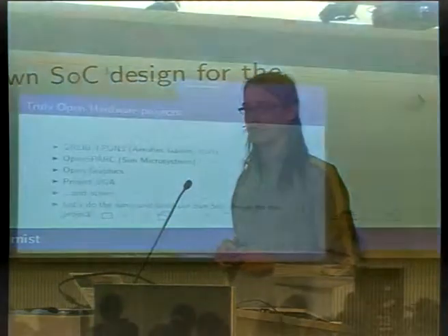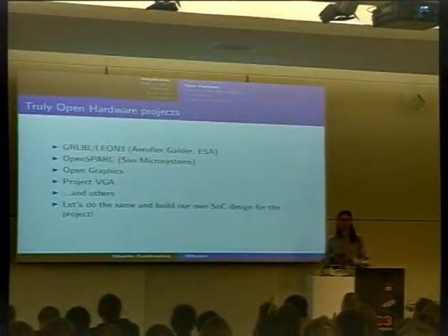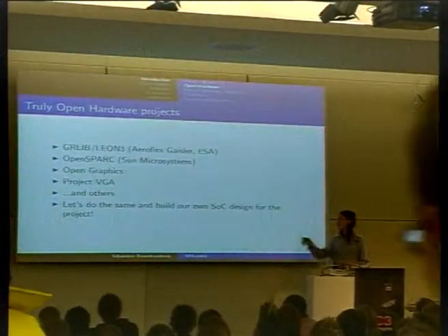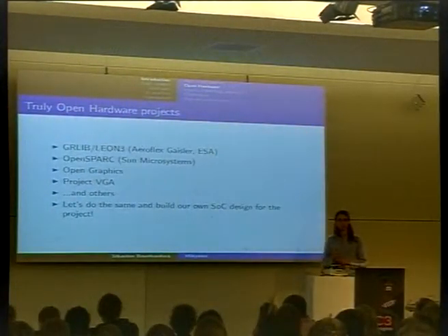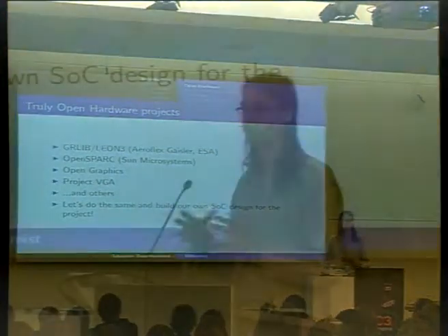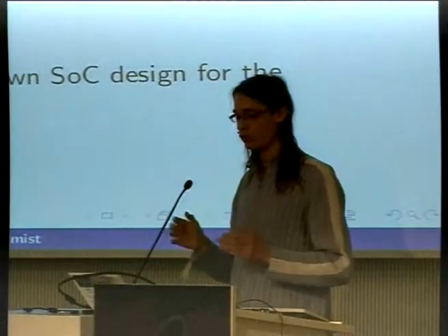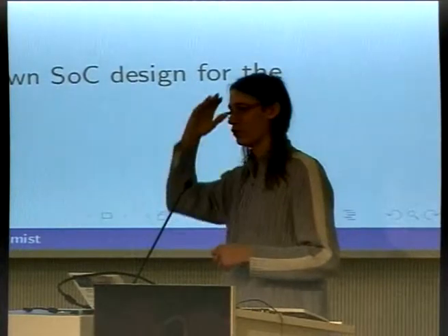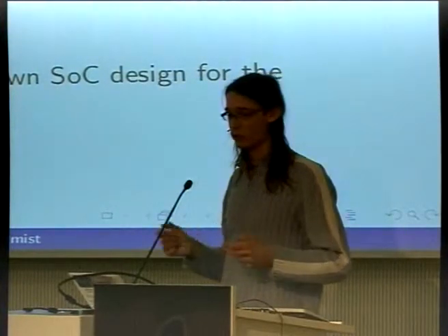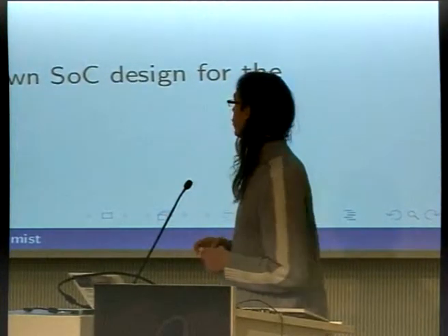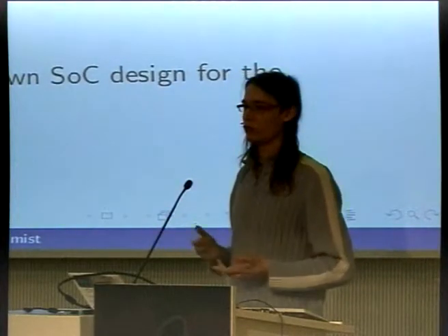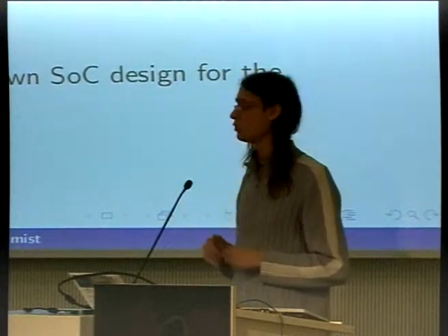OpenSPARC is a very complex design which has many optimizations, and sometimes when you are doing FPGA, it's better to have a simpler processor which could run faster, because when you implement all the features which are in OpenSPARC in an FPGA, you get very complex logic functions with many levels, and the clock frequency goes very low, and it also eats up many FPGA resources. So OpenSPARC is not very accessible to hobbyists.